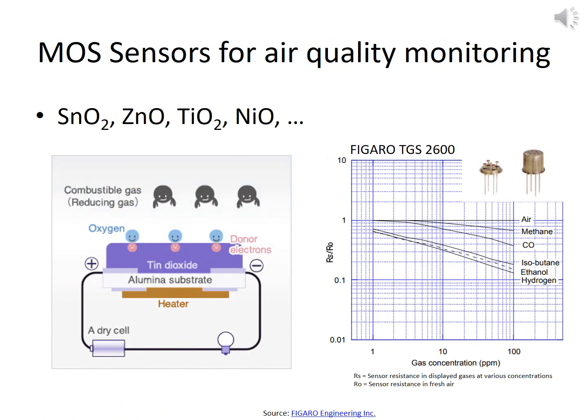As referred, metal oxide semiconductor sensors based on conductivity variation have been used to monitor pollutants for a long time due to their semiconducting properties. Besides the already mentioned titanium dioxide that has been used extensively for gas sensing applications, tin dioxide is undoubtedly the most studied material and it has been applied to many commercial devices on the market.